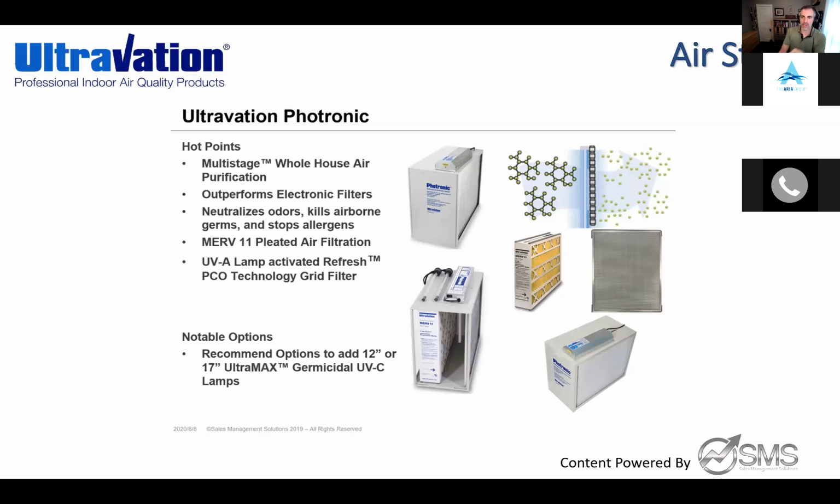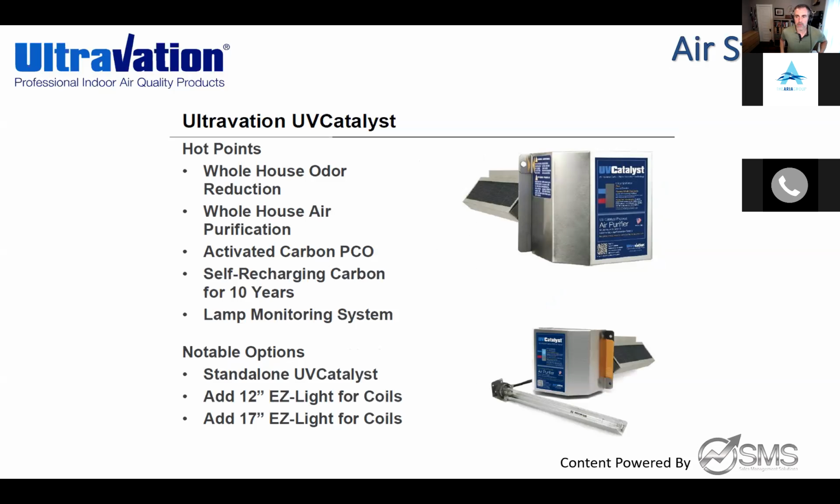So we're going to finish off the high-end residential now. UV catalyst. I actually have this in my house because in the next year or two, my wife and I want to flip this into a rental and move to another home. And I just didn't want to ever worry about anybody being concerned about any kind of ozone at all. So I already had the 2 UVC bulbs in the coil. Technically, if I switch those bulbs out every 2 years, if they weren't T3, I'd have to worry about that ozone off-gassing.